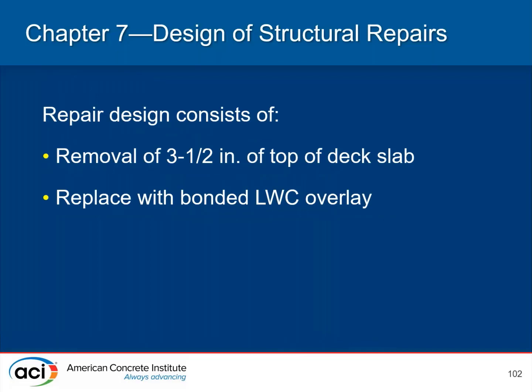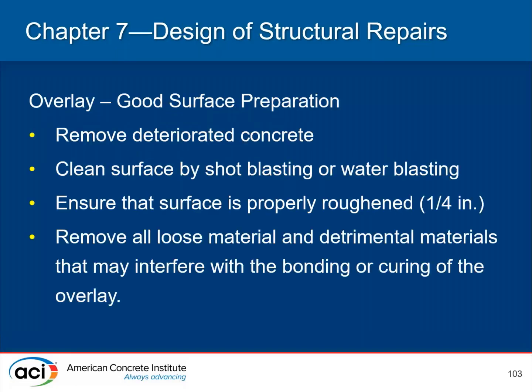So the repair design consisted of removal of 3.5 inches of top deck of the slab and replaced with a bonded lightweight concrete overlay. So for any overlay, and overlays can be one of the most challenging operations because you're dealing with, generally speaking, a large area that has to be adequately prepared and oftentimes time-sensitive operations.